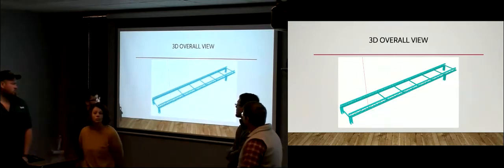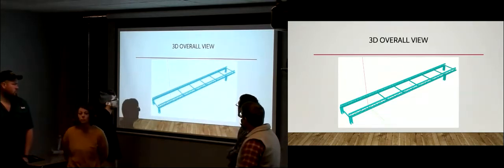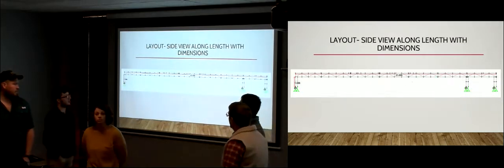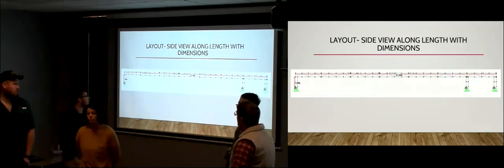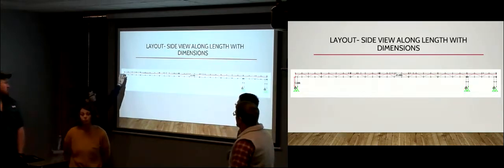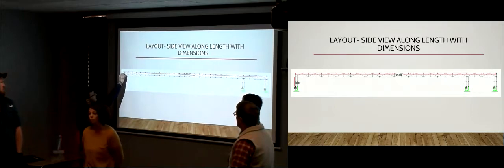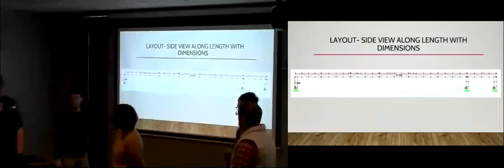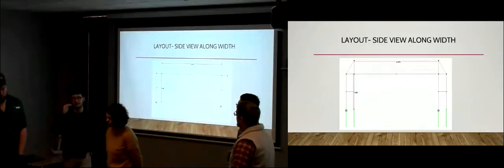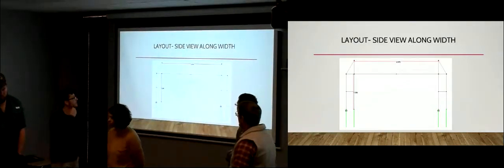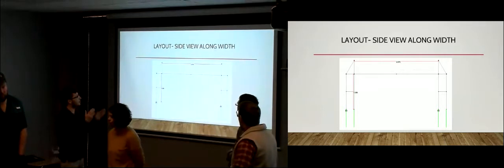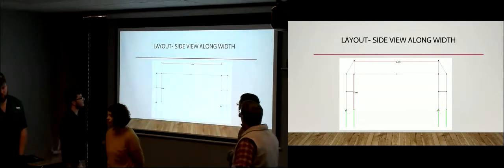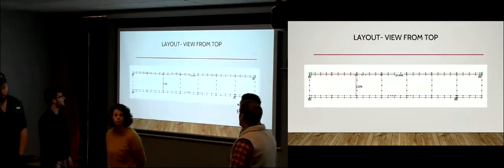Originally, it did not look like this. There were a lot of optimizations that went into this. The overall length I used was 23 feet, and I tried to get to the bare minimum of height. So my footings were 13 inches, and then from there to the top of my loading rails was the other 6 inches, to make it exactly the bare minimum 1 foot 7 inches. I tried to do the bare minimum width as well at 2.67 feet.